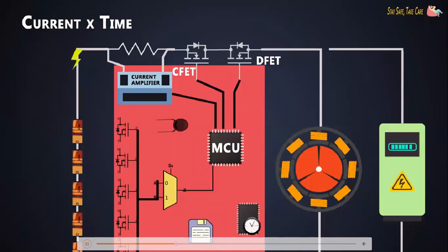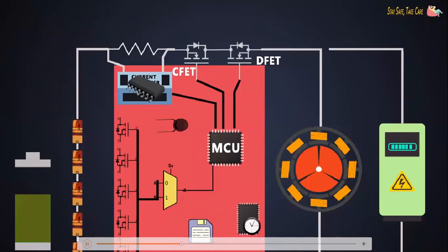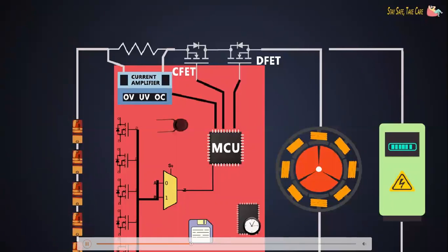The discharging and charging current is sensed by the direction of current. If the current is coming inside or going outside, that means the battery is charging or discharging. There are certain fuel gauge ICs available in the market which take care of the SOC, and many times using a fuel gauge IC adds additional cost to the BMS. In case of an electric vehicle, using a shunt resistor is always the best option.